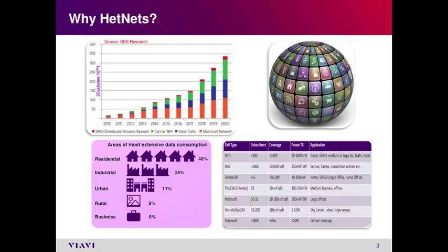For example, a macro cell, which is much more significant, as you already know, is like 43 dBm, and the coverage can be in miles, whereas a Wi-Fi network or a femtocell network can be much smaller. It can be a single office or home office, with power transmitted in milliwatts and coverage of square feet. So this varies, and how all these different technologies have to work together, that's the basic definition of HetNets. Even in 3GPP, standards are already defined, and things have started to work harmoniously to get HetNets, basically a head start in my mind.